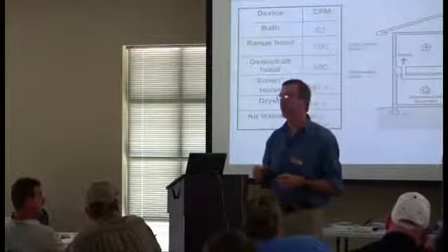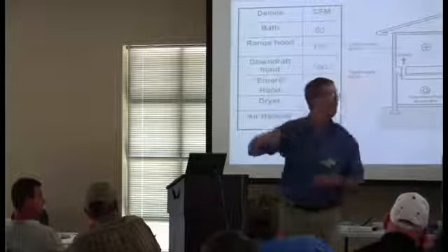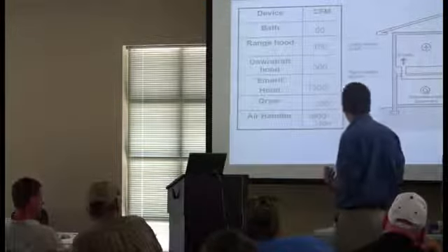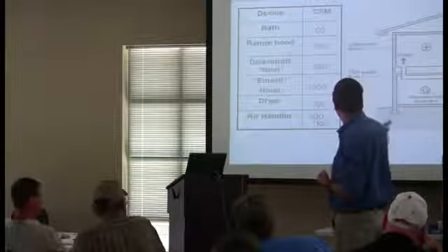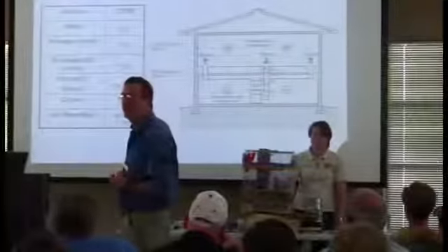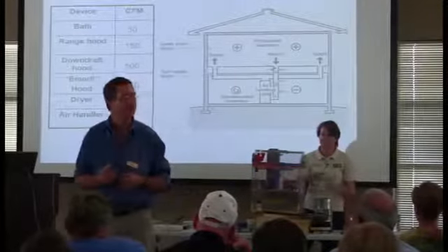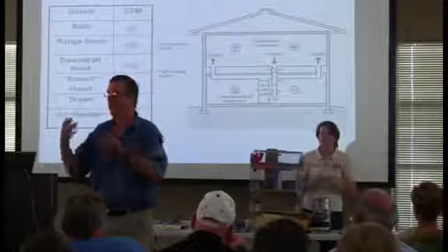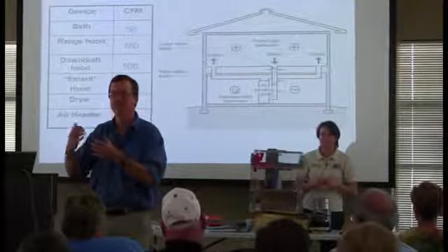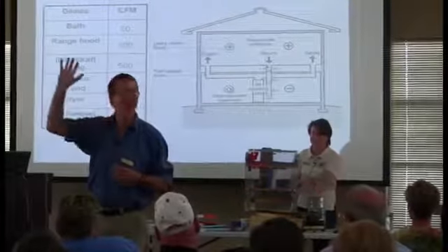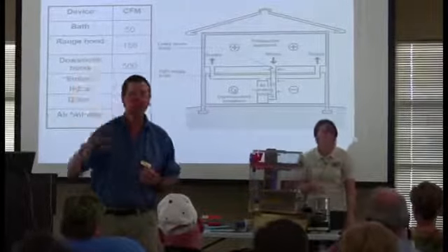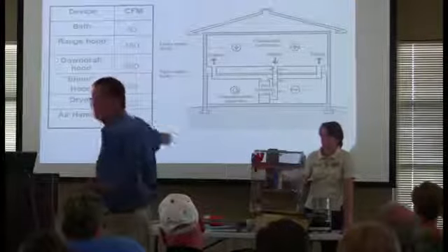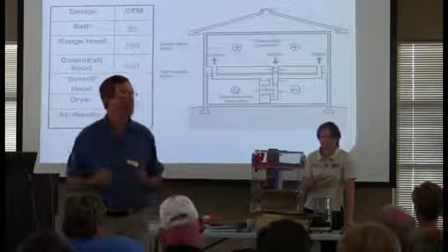Where are all the supply ducts located? All the bedrooms, right? So everything works great. Okay, Roxanne, everything's working fine until nighttime. We close the bedroom door. What happened to the pressure in the bedroom where the supply duct is? What's the pressure like? The blue side. Is it positive? So what does that mean? If there's a hole, which way is air going? You're throwing conditioned air out. Air will find the path of least resistance, it will leave. And if, let's just say, 150 CFM is leaking out the bedroom side of the house, what has to happen somewhere else?